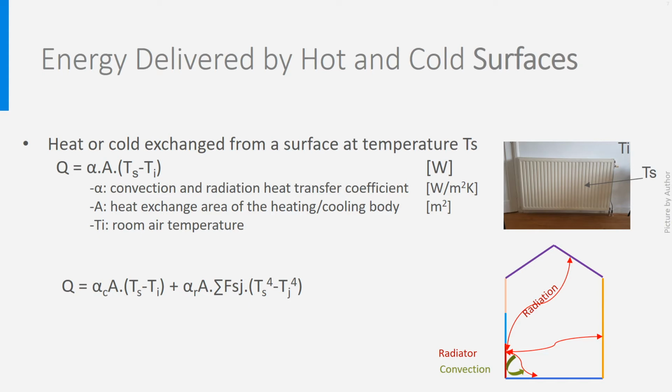Furthermore, the heat exchanged by radiation between the radiators and the other surfaces in the room will, for a large part, end up in the air, as the air is continuously licking the walls, taking this way their heat. So, although it is physically not completely correct, it is of good use to describe the heat transfer from such a radiator with this equation, separating the alpha coefficient into a convective part and a radiation part, and using the air temperature instead of the wall temperatures.